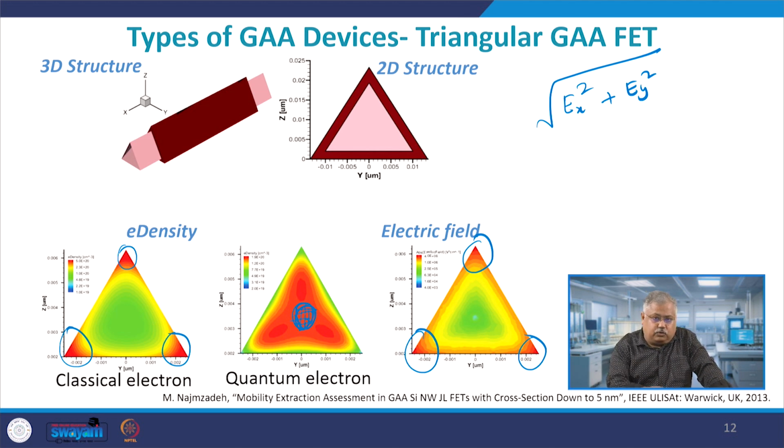So, we will stop here today. What we learned from all this discussion is that we require a high-K material. We also require that the channel should be surrounded from all directions for reducing the short channel effects, for example DIBL, gate leakage current, direct tunneling current, and so on and so forth. Further, if you reduce the oxide thickness to a very low value, the direct tunneling current takes precedence over anything else, because of which the off-state current actually increases, right. So, when we meet next time, we will discuss further areas of GAA devices.